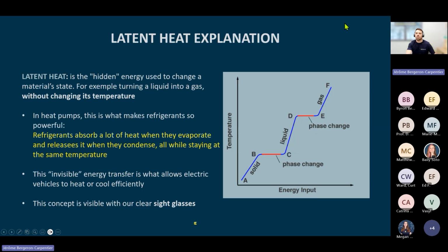So the reason why it's super important to talk about latent heat and understand what it is, is basically that the moment we are changing phase, we keep adding energy. And that extra energy is going to be super useful for either subcooling, superheat, so to release that energy back to the system. Okay?